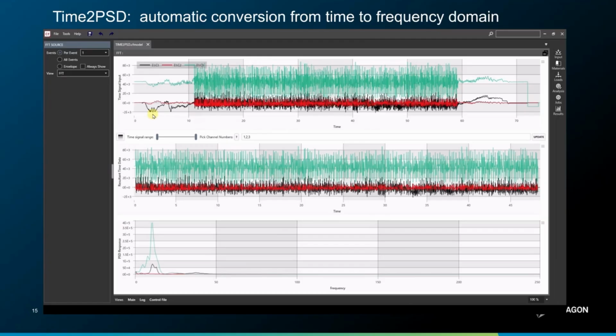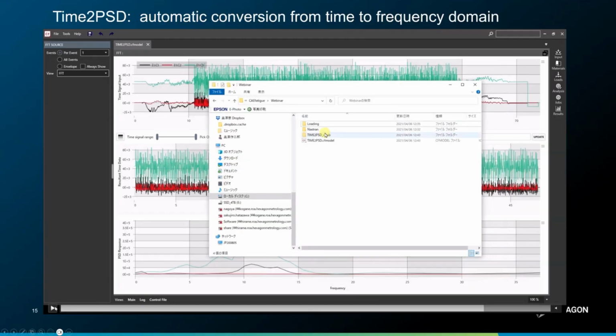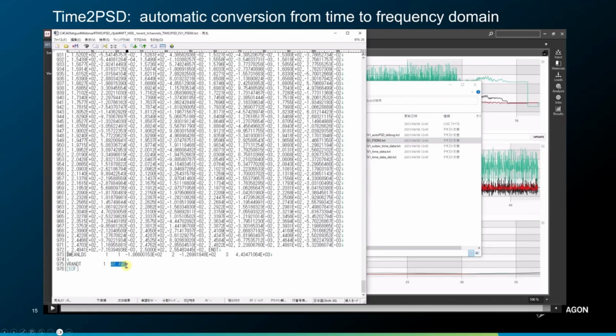because it cannot be left to the interpretation of the buffer, the windowing, and the FFT algorithm, right? We have a way to make this process very repeatable and very consistent. Ultimately, as I mentioned, we can look at this now and create envelopes and use the envelopes. If you want to do something very simplified, we can take this result as a random table that you can flash back inside Nastran, or you can use this directly inside CAEfatigue for a more advanced cross correlation case.